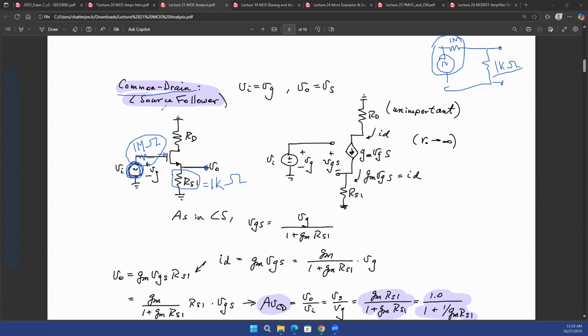So you have heard about, for example, amplifiers or op amps being used as a buffer, right? So your gain will be equal to 1, but you'll have better driving capability. A buffer or a driver has better driving capability. So that is the use of this common drain configuration in any amplifier-based circuit. And that's why in the exam question, your second stage is this common drain, not your first stage.